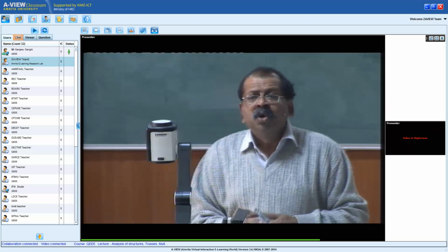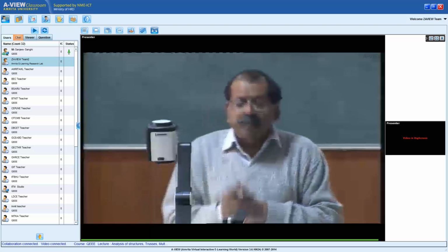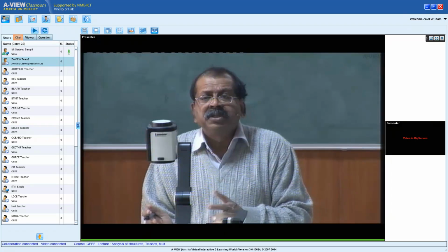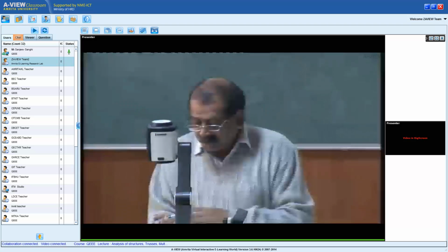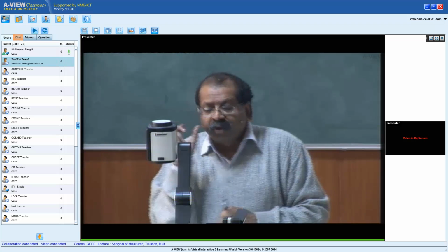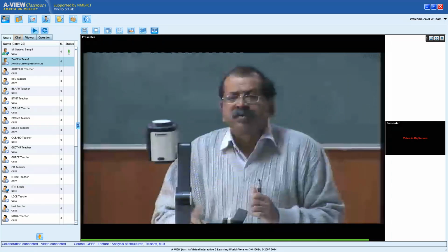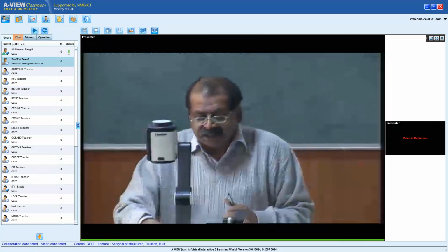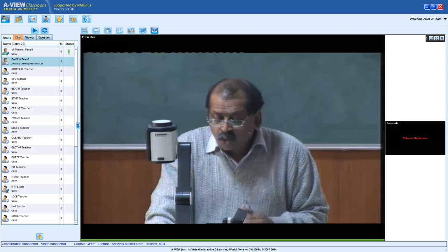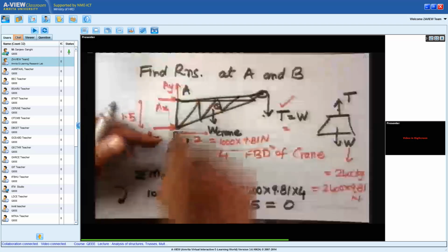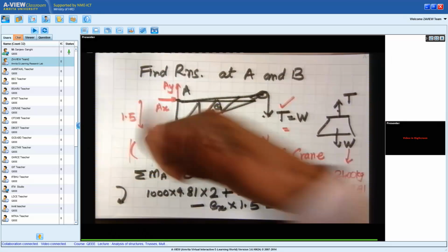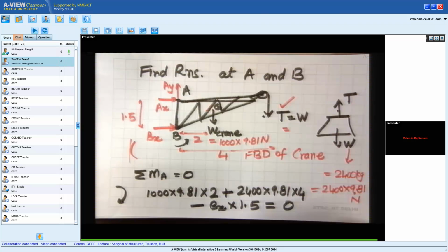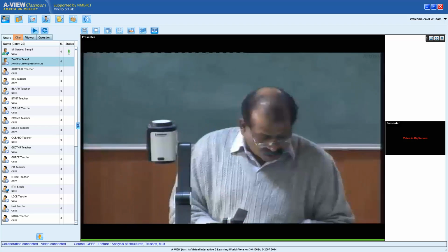Things like this you will have to do in solving problems of planar nature, and there you will be able to take moments by just taking a vertical and a horizontal component of the force. If it's a vertical component of the force, you have to take the horizontal distance. If it's a horizontal component of the force, you have to take the vertical distance and get the right sense from R cross F. You move to the point where the force is being applied, so that is R, and then you turn your fingers towards the force, in the direction of the force. If the fingers curl in a clockwise direction, the moment is clockwise. If they turn in the counterclockwise direction, the moment is counterclockwise. So you work this out.